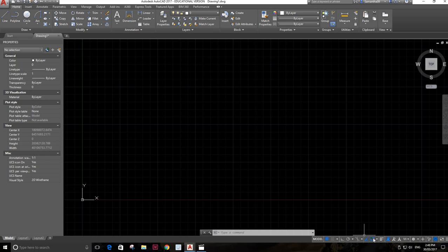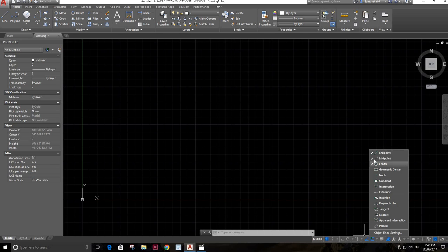It's a really good status to have on. And you have this thing here called Object Snaps. This is also equally useful. You can see a little down arrow there. Click on that, and it has a whole lot of different types of points that can be ticked. You can see my endpoint, my midpoint, and my center point is ticked. Whenever I'm making a drawing and I want to close off a drawing, it'll click back to the endpoint. If I want to find the center, I've got my midpoint on, so it'll always find the center of a line or a center of a circle, etc. Sorry.